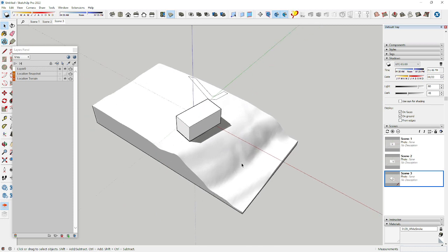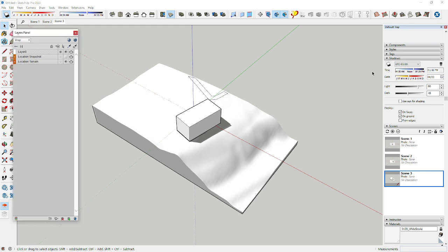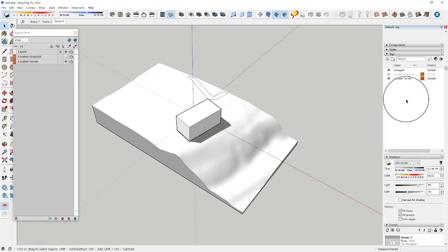And then I can export this whole thing as a complete model into Rhino. When you do that, and like I say, I would have very carefully organized anything I put in this model into layers and sublayers. I have this old layers panel thing I use, but you can also, of course, just do it with tags. And then those actually get transferred also into Rhino, but the objects usually aren't transferred to the right layer, so you've got to move them around a little bit, but it's pretty easy. Anyway, that's what I'm talking about.